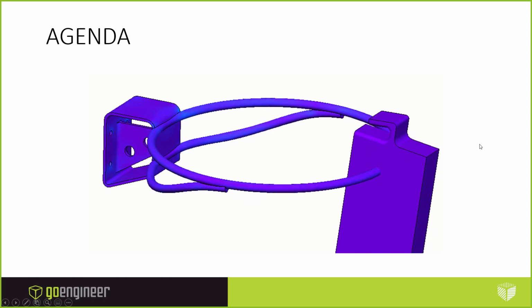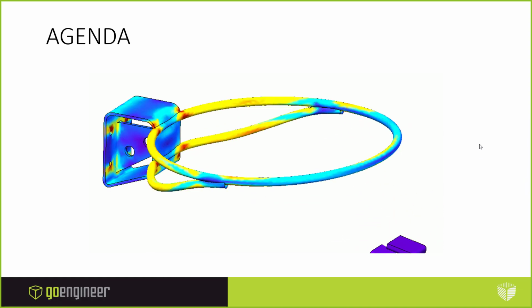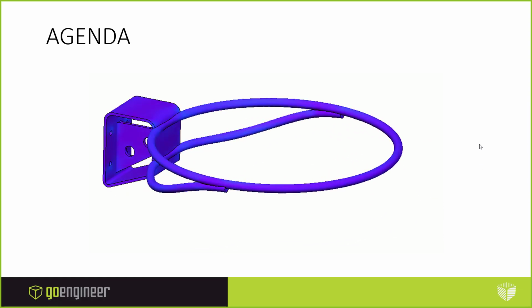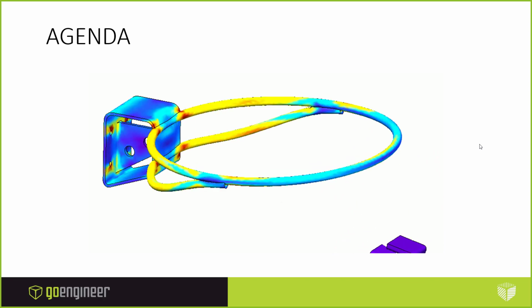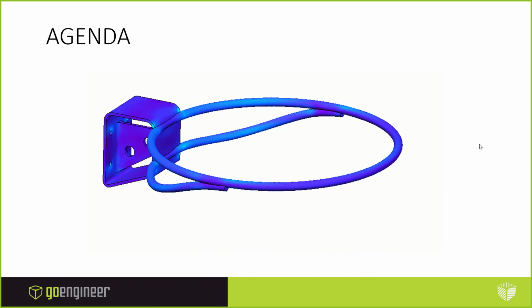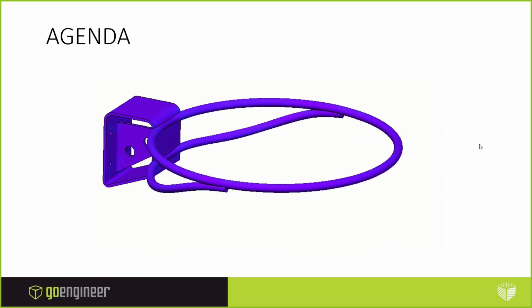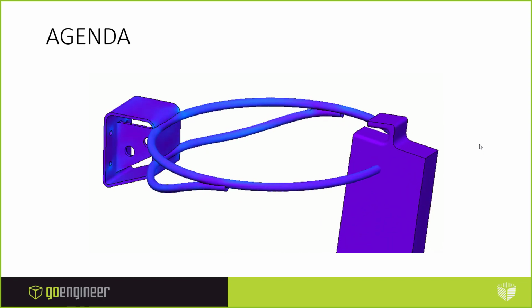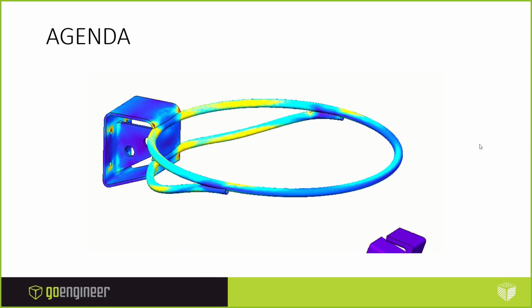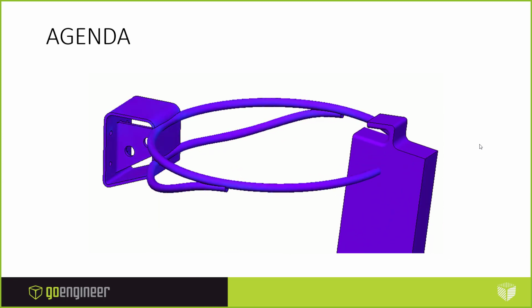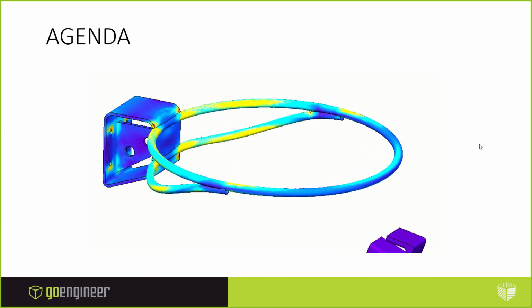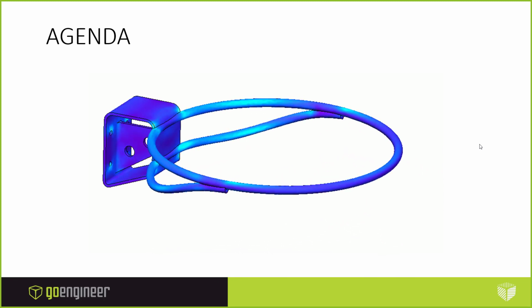Here's the full-blown animation. Oh no, pardon me. This is a different animation. This is an animation showing what if I start this thing higher up. If I start at 6 inches off the surface. So in other words, I jump a little extra high, 6 inches higher than the hoop, and then I come down onto it. You see it creates even larger displacements, very large stresses too. And you see that contact it makes as it releases too. Goes up, high frequency vibration, hit it, more high frequency vibration.